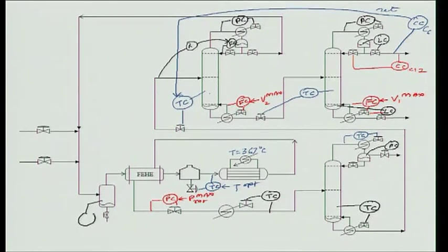Well, I have got level control this way. What about level control of this one? Well, I got level control this way, local pairing. Now, I have a problem in the sense that, what about this level? You will notice that I have basically used up all valves that are local to this column. What about the level of this one? You will again notice that there are, oh well, I forgot a loop, just a sec. So of course there is level control here this way.